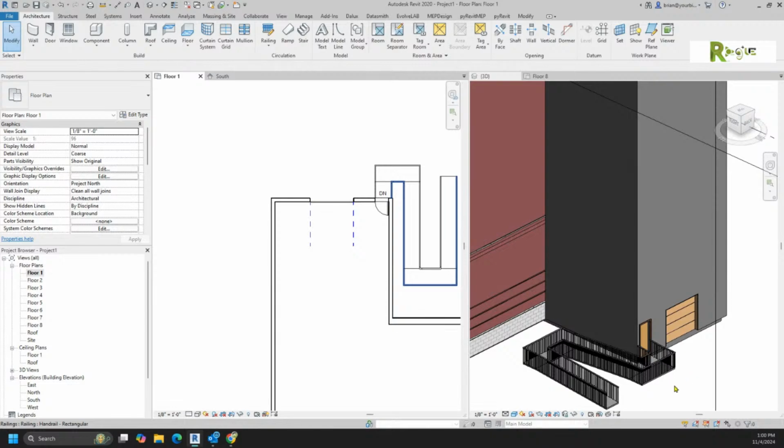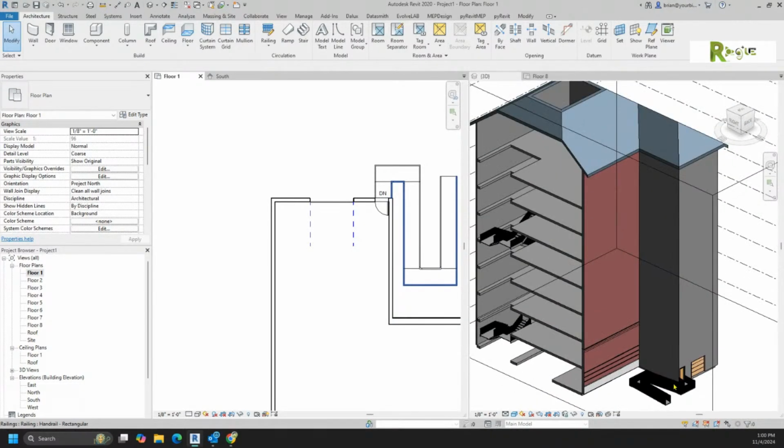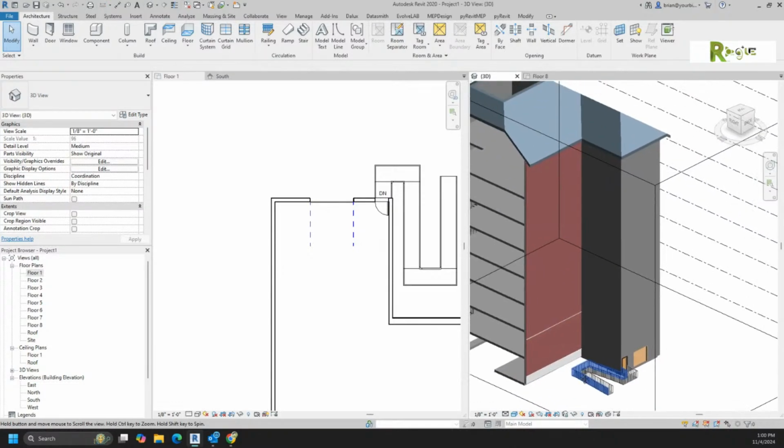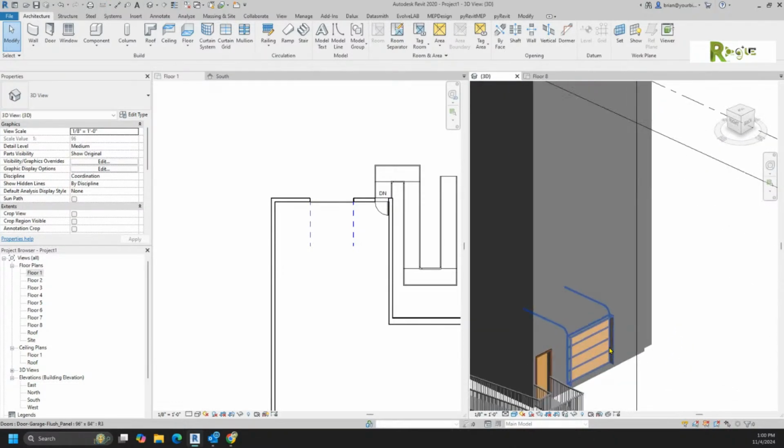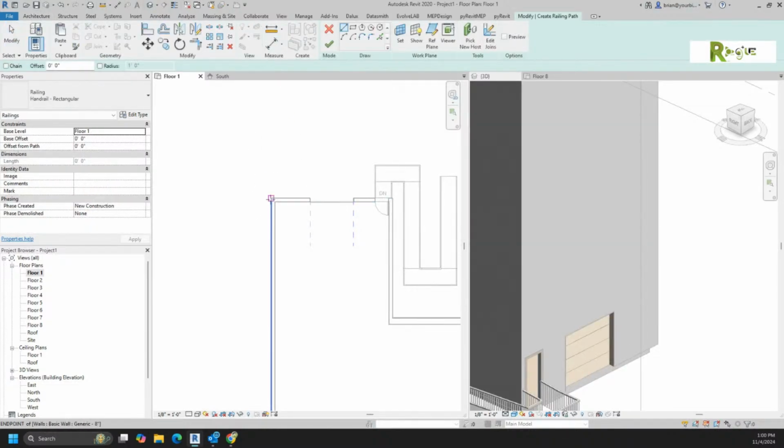And both the stair and the ramp automatically get a handrail. But if we had an opening, like this was a loading dock, we could put a railing in there as well, like around here and up to here and over to here. You see the chain, how it's checked off? That's typically by default how the handrail is. It may be different on yours, but the handrail is one of the few sketches that does not have to be closed.